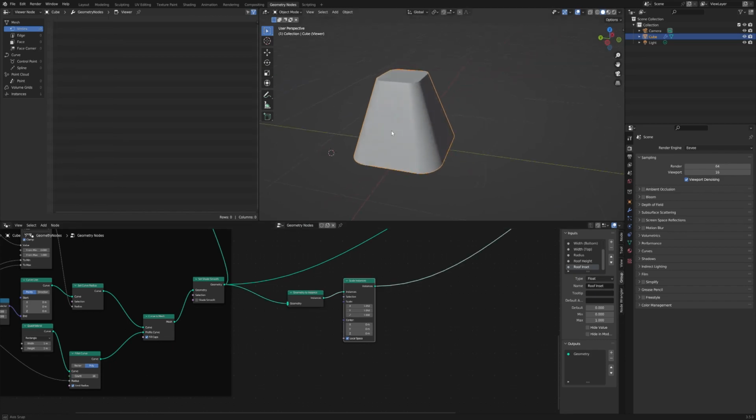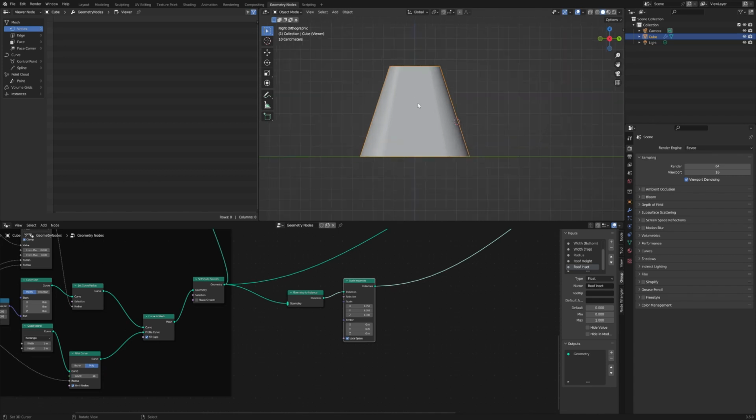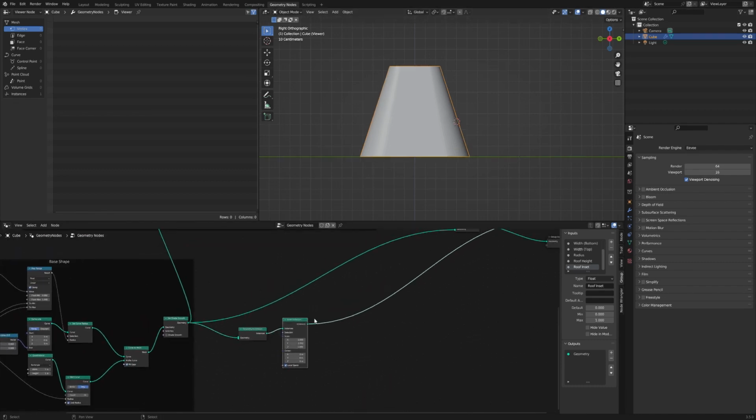And just so we can see what we're working with, as we're moving around, you can press 5 to change this to orthographic, and then 1 or 3 will give you front and side views. The reason I've done that is so that you can see the difference before and after we scale. What that allows us to do is take this bigger shape and make some cuts in it with some more Booleans and actually make our steps, and then add the scaled shape, which will have cuts on it, to the base shape, and that will give us some nice stepping. So it's essentially going to be 2 shapes on top of each other, but at the end of it, look like one.